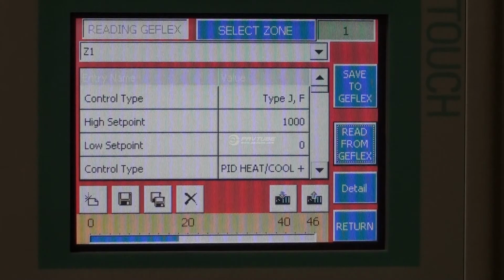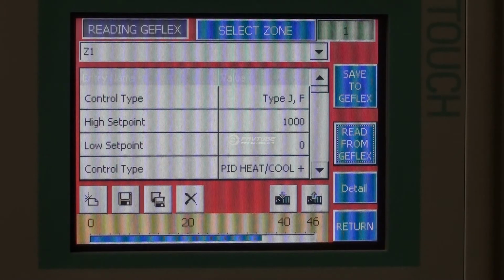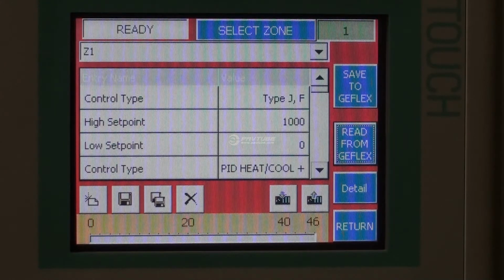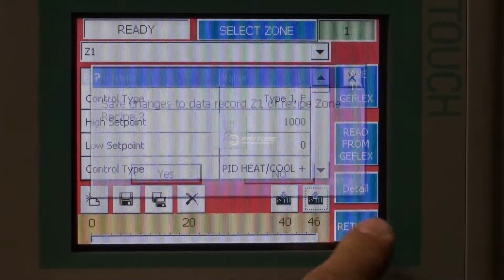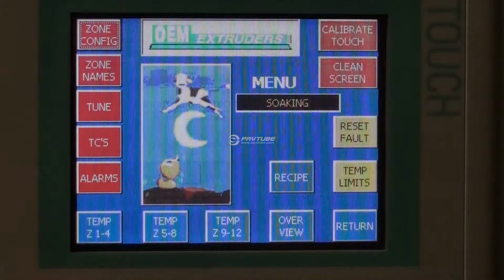operation. Now what it's doing is writing it into the PLC. In order to see it up on the screen, if you suspect that something might be set wrong, you would upload it right now like you're doing into the PLC, and then we would upload it to the screen. And you can see exactly what was inside the JetFlex unit. There's also a small module we can plug into the bottom of the JetFlex units to individually go through the zones one at a time with a little handheld controller and set parameters with that. And let's return here. We don't want to bother saving it.